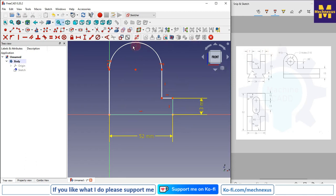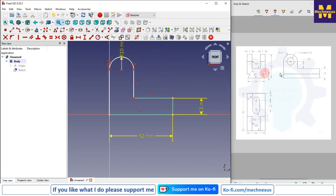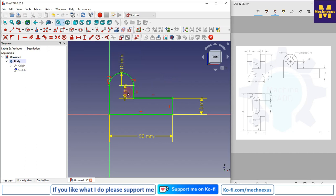And this radius is R10, so I will select this arc and give the radius dimension 10. And from this edge to the center is 10 mm, so I will select this line and give the vertical dimension 10 mm. Now I will move my dimension outside.